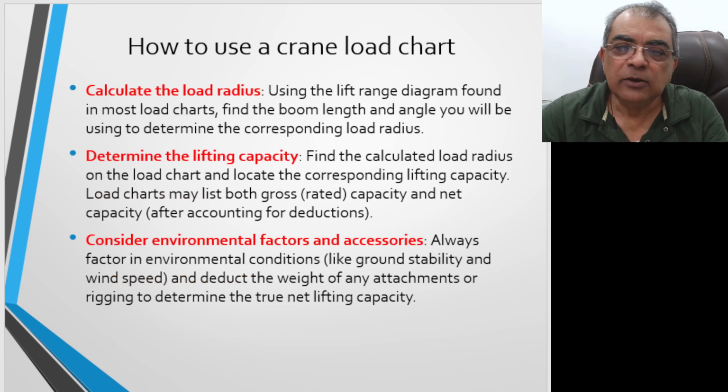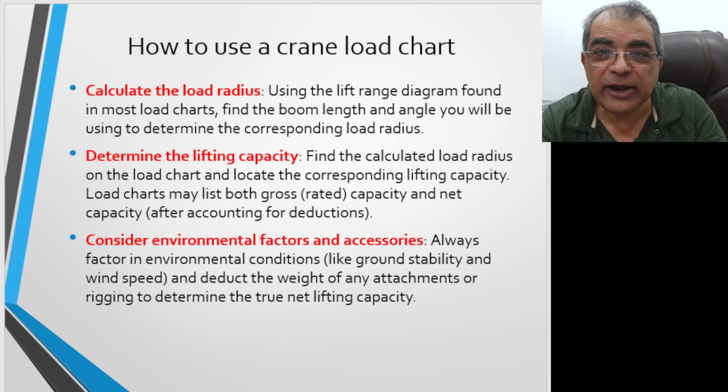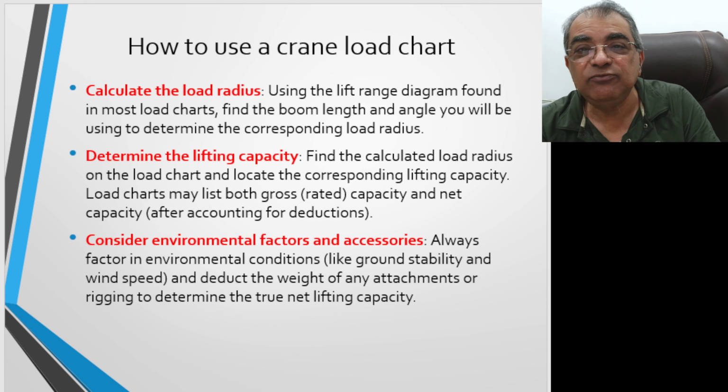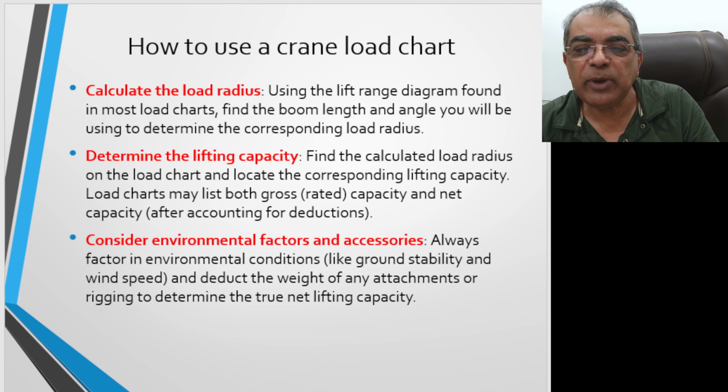Okay. So how to use the crane load chart? Calculate the load radius as I have shown you in that one photo. Determine the lifting capacity. Find the calculated load radius on the load chart and locate the corresponding lifting capacity.